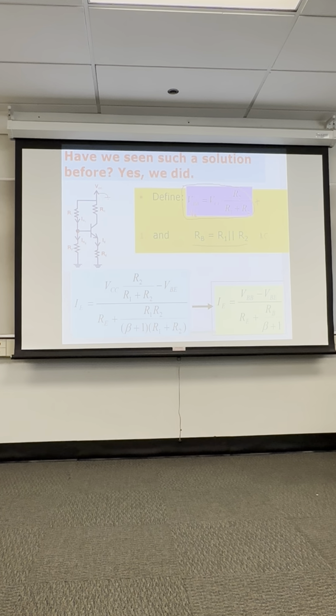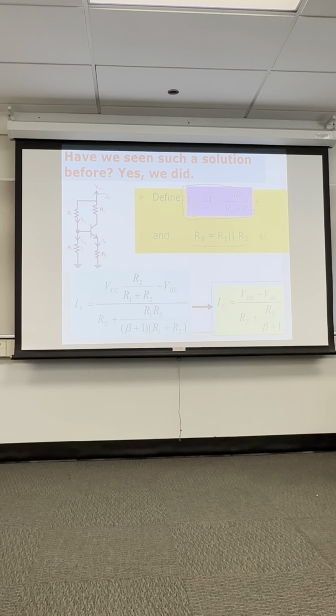And now, if we solve for the current over here, you notice these arrows are just saying there's no current going into the base. In reality, there is a current. But we can solve for the emitter current here. That's in this loop here. Solving for the emitter current becomes this equation, and then eventually we get it in this form over here.